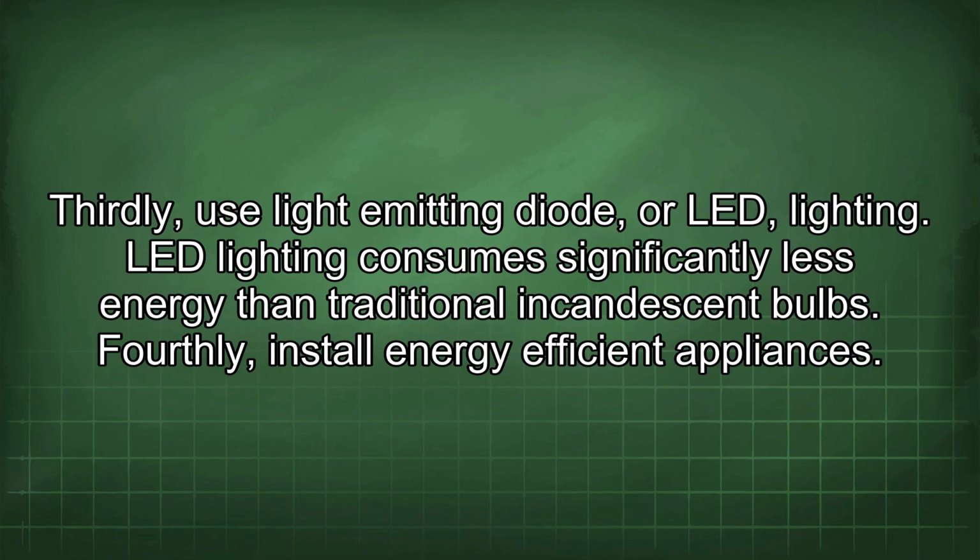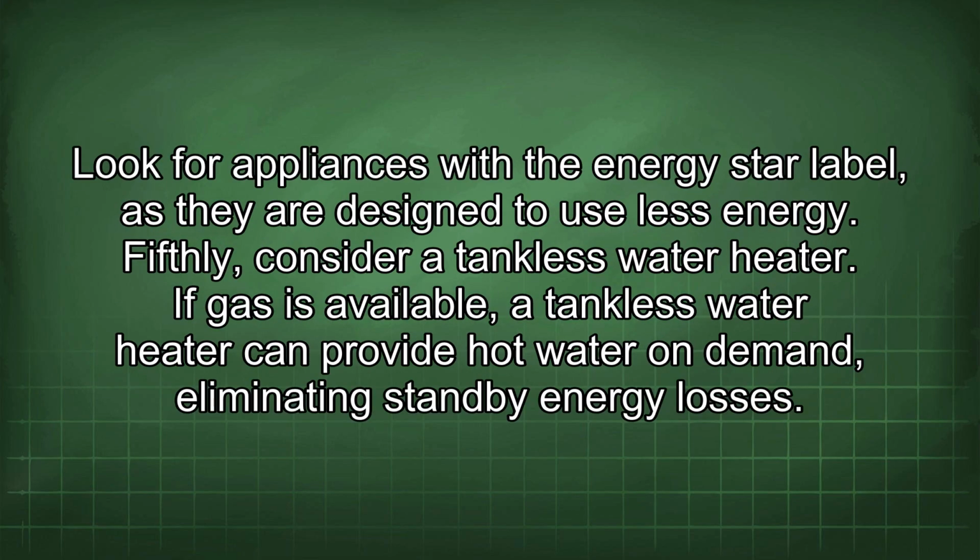Thirdly, use light-emitting diode or LED lighting. LED lighting consumes significantly less energy than traditional incandescent bulbs. Fourthly, install energy-efficient appliances. Look for appliances with the Energy Star label, as they are designed to use less energy. Fifthly, consider a tankless water heater. If gas is available, a tankless water heater can provide hot water on demand, eliminating standby energy losses.